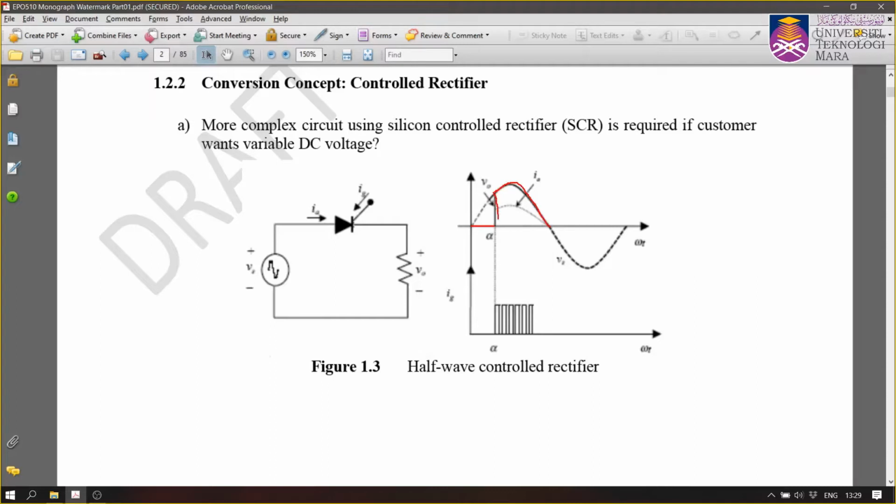So this is the output voltage, and during the negative half cycle it will operate as the diode. Whenever you see that this is reverse biased and current starts to flow in that direction, the thyristor here is an open circuit again, and therefore there is no current flow. Output voltage equals 0. So therefore you see a 0 voltage here. So that will be the output voltage.